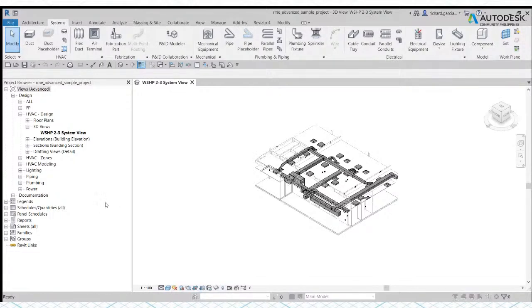Just click the options here, and then you go to the graphics. Click the graphics. No, it's user interface. Okay. So you go to user interface and then you can now see here the tools and analysis. So as you can see here, the structure tab is unchecked. But if you are a structural guy, of course, you need to check that one.